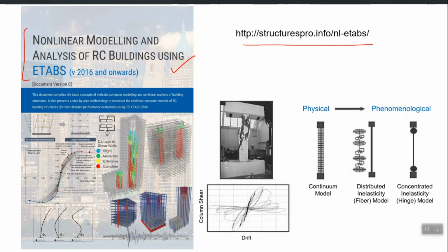In order to make that model damage aware, we have to give all the capacities in it as input. We have to tell that program at what bending moment all the beams will yield, and at what shear force all the columns will have shear failure. So all the capacities at material level, at cross section level, at member level should be provided as input in a nonlinear model, which means that developing a nonlinear model requires far more inputs compared to a linear model.